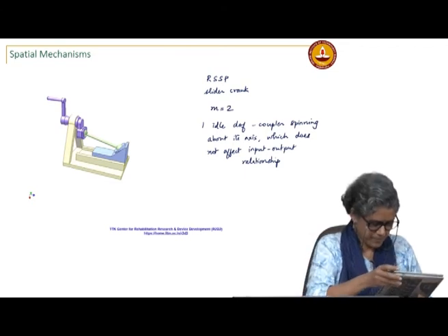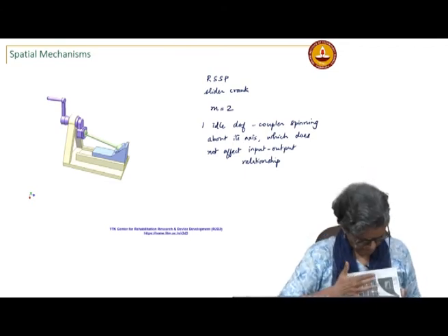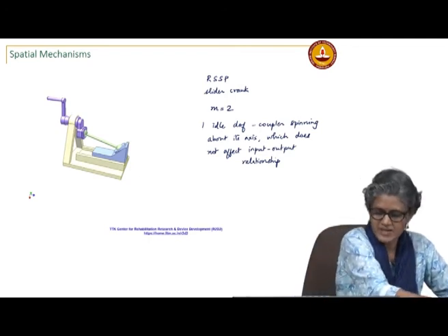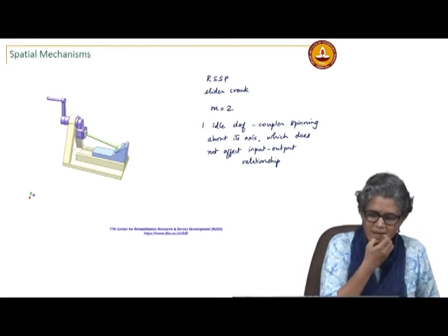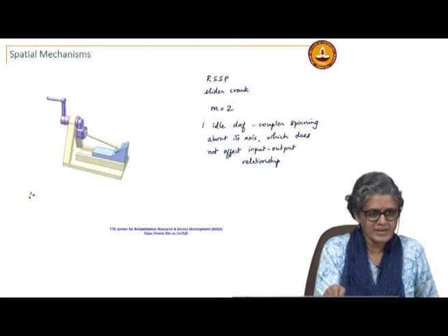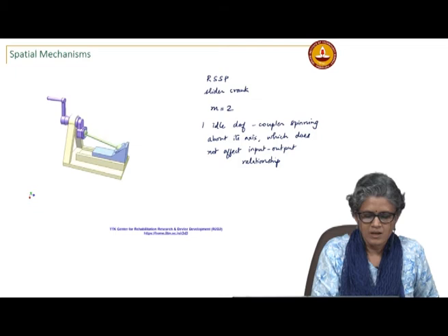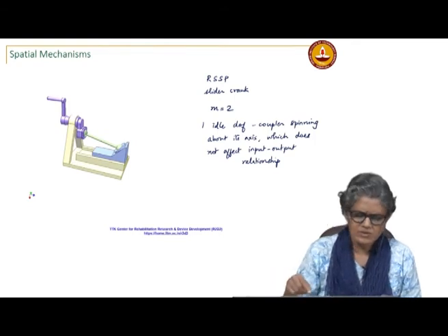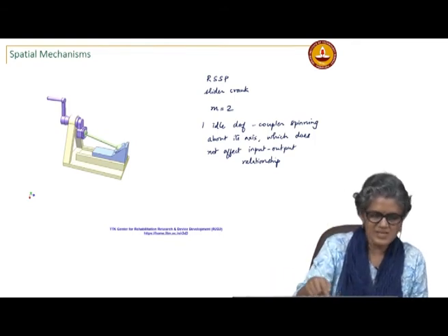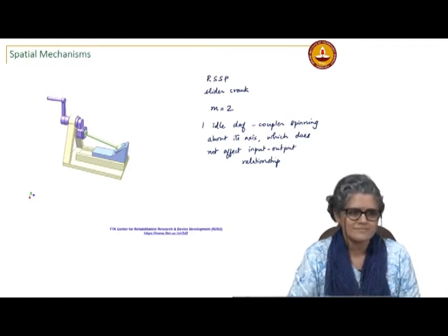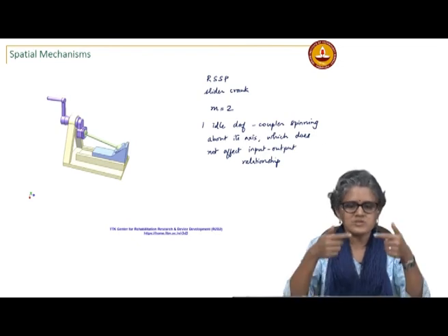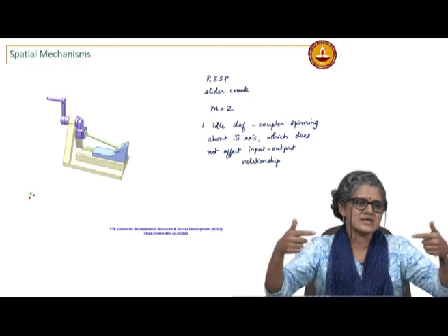In this slider crank, if the prismatic axis and the revolute axis are aligned, as in coincide, the slider won't move. Right? Why is that? Because it is a singular point, no? Still, because everything is in line, it is like a toggle position, right?